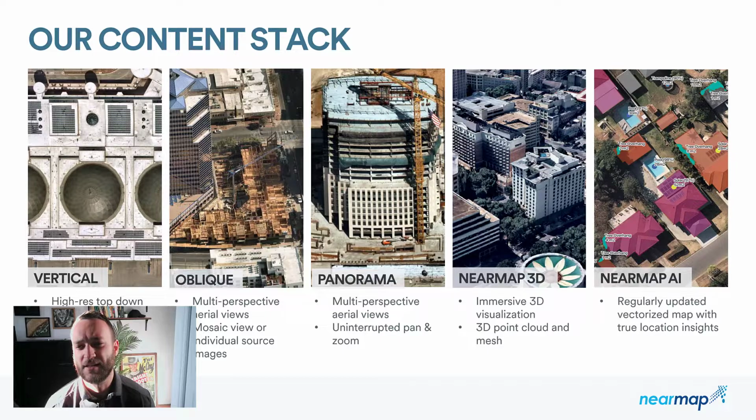These are raster data sets, so you can think of them as essentially point data that CAD and GIS programs can read to set elevations of existing grounds. You can use them for terrain models, do things like cut fill analysis, profiles, cross sections, and I'm going to show some examples of that a little bit later on as well.